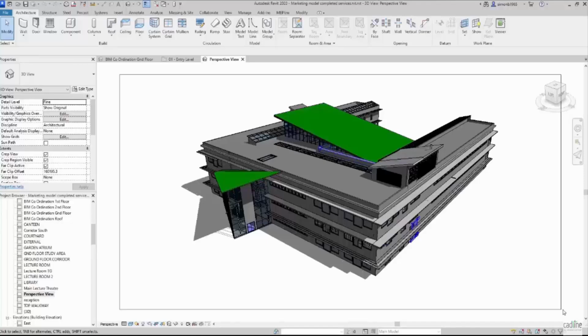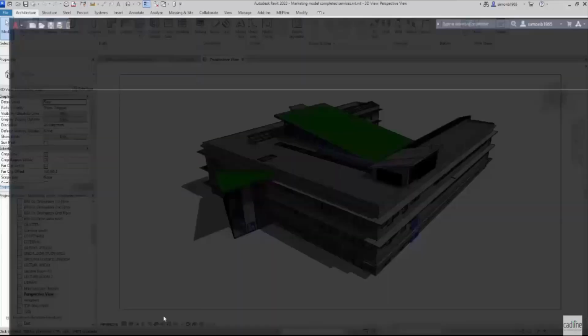So effectively when we go into the MEP Works site plan program, we're going to specify each point of this geometry to build up the vertex, so that we can then accurately create the geometry on the building. So effectively we would DXF out all of the floor plans as normal, set up the model in MEP Works as normal, and we'd also introduce the site plan as well. Now Revit may well have a site plan, and exactly the same applies if you're sourcing your drawings from AutoCAD.